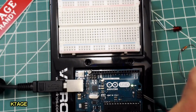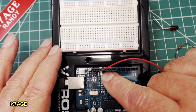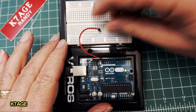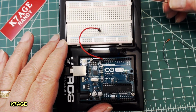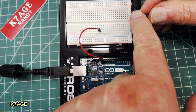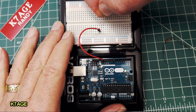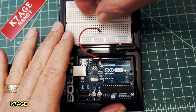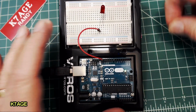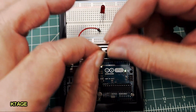So the LED is on pin 13 on the Uno. I'm going to put a jumper cable in there. I'm just going to pick a pin over on this side. And here's the LED. The long pin is the anode, so that'll go towards the positive voltage. I'm going to plug the longer lead in the same row as the red wire that goes over to pin 13. And now I have a 330 ohm resistor because I just happen to have one laying around.